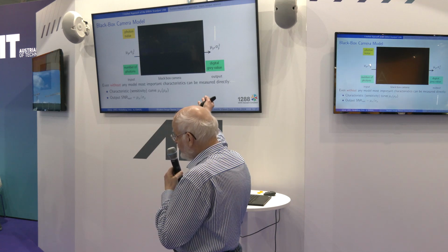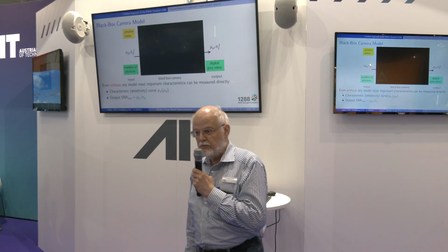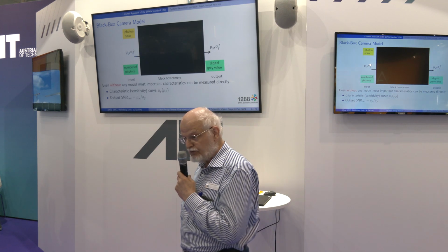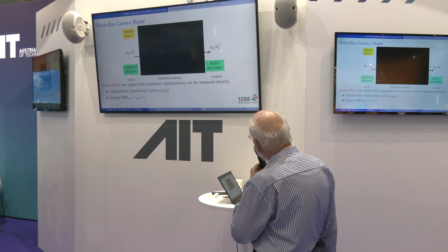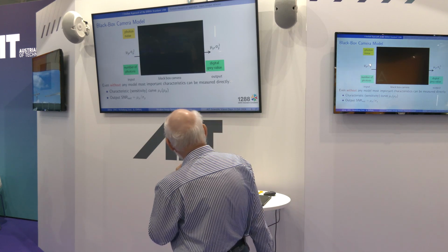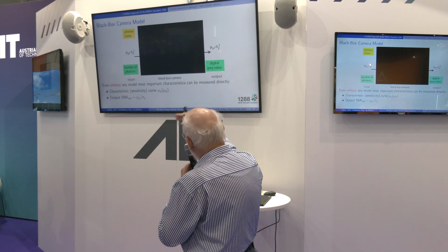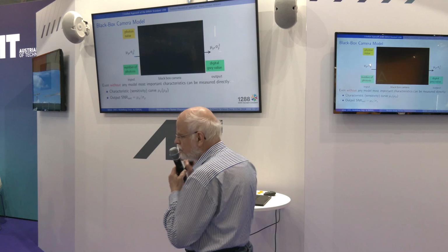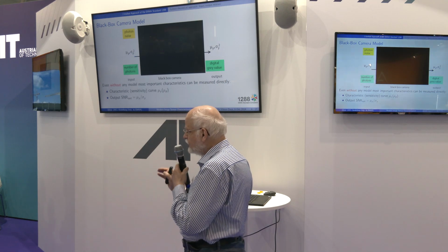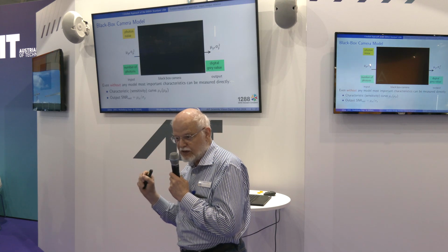Then additional noise sources may be in the camera, and they influence both the mean signal you get and also the variance of your signal. So this is always in mu, a mean value, and in sigma squared, you have the variance. And without any model, you still can do two important things. The first thing is you can measure the so-called sensitivity or characteristic curve.